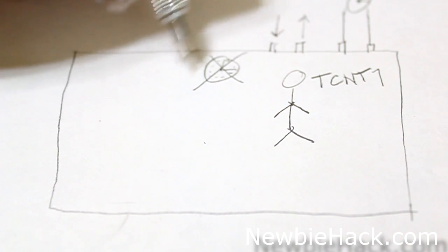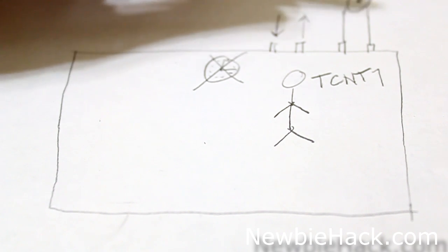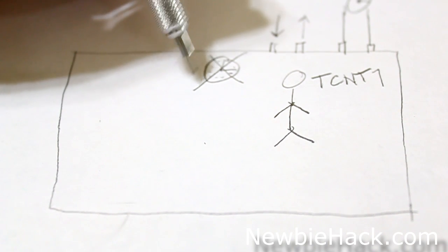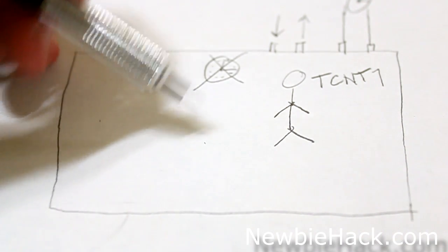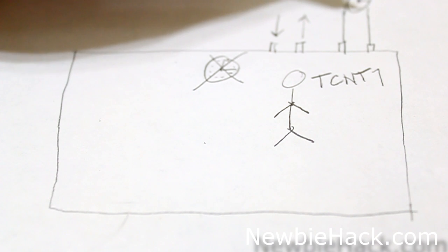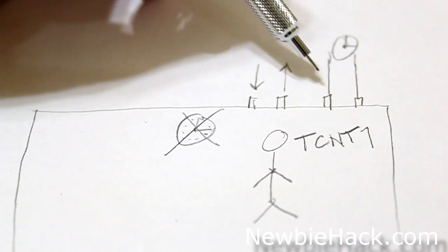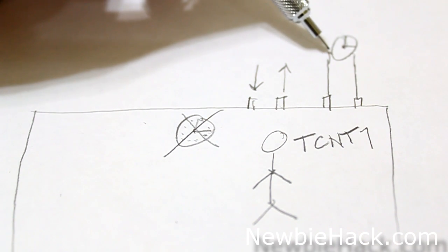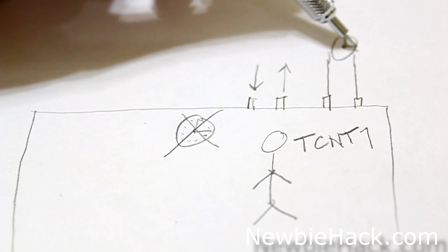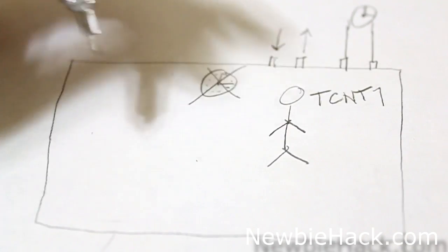Generally, the clock that's inside of the AVR is not as accurate as an external clock could be. The clock that's inside the AVR has an error of about plus or minus 10% of its timing. The external clock could use a crystal, like a quartz crystal that is used in clocks or watches, and it will give you much more accurate time. But right now we're just going to use the one that's internal.